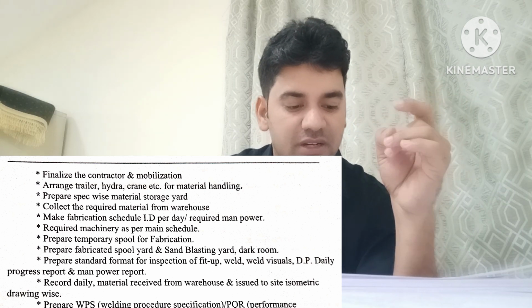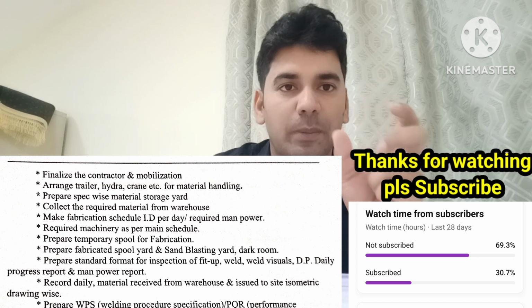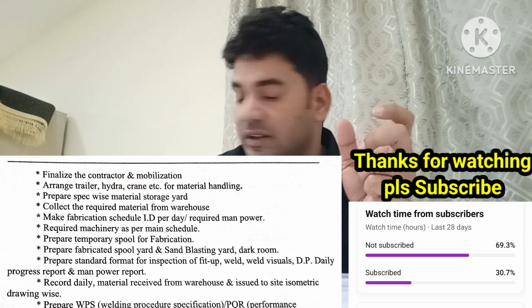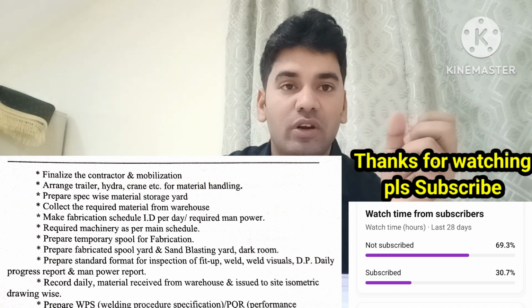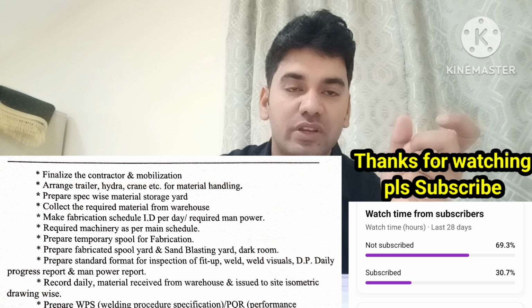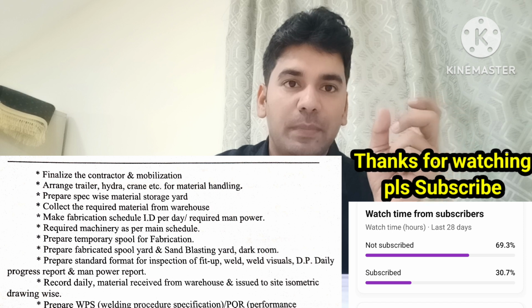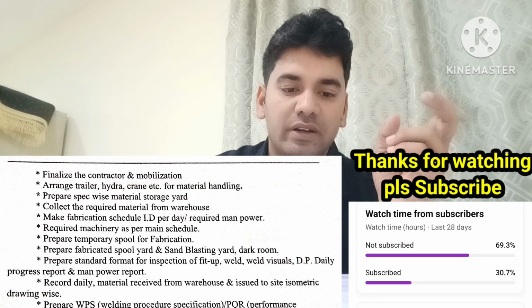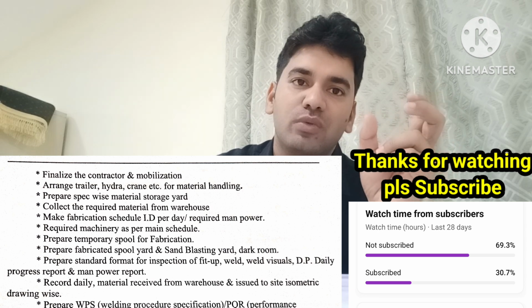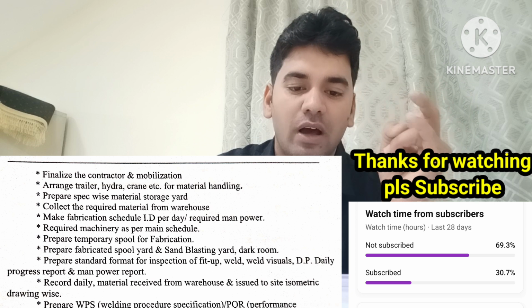Prepare a standard format for the fit up inspection, welding, grinding, that kind of activity, and also for the manpower report. Record daily material received from the warehouse and issued to site as per the isometric drawing. Prepare a WPS, welding procedure specification, PQR, procedure qualification record, and the welder test, WQT, welder qualification test. These all need to be prepared.